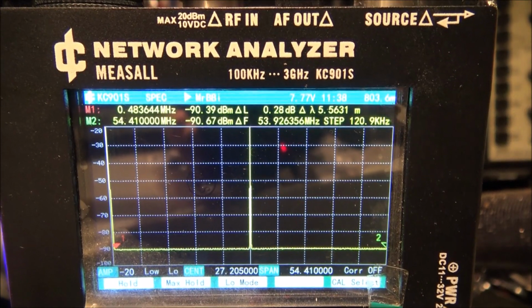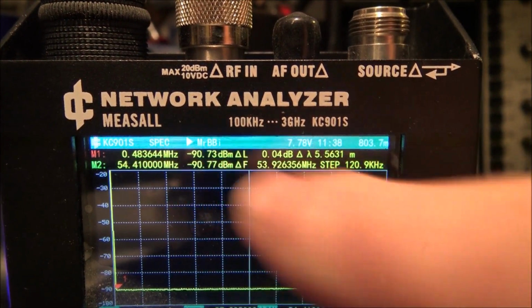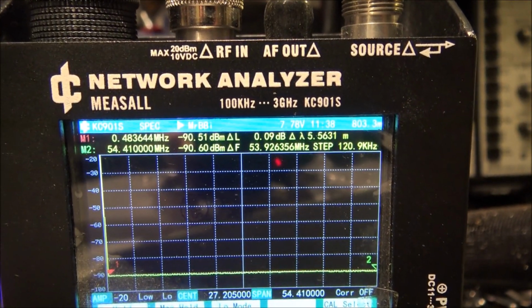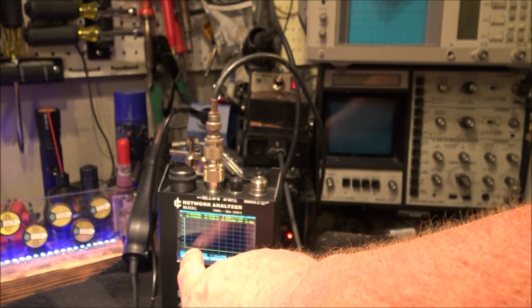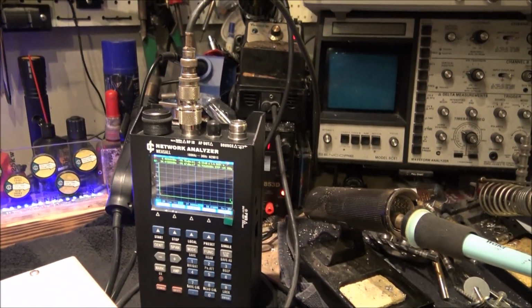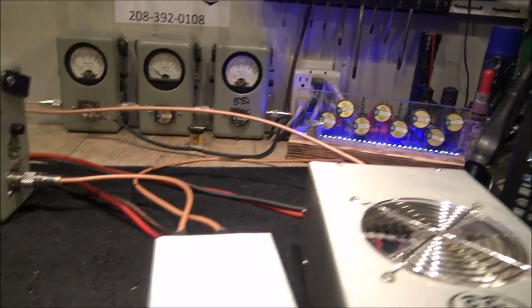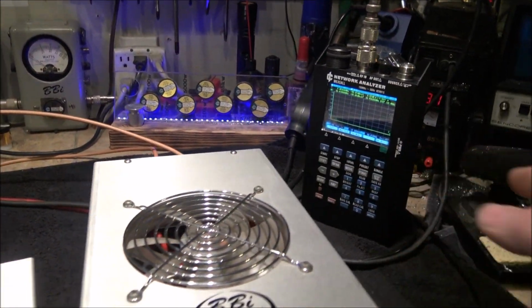And up here in the corner, you can see our signal reference. Okay, that's our noise floor bottom. If there's any kind of signal that is present out there, like I just seen a little bit of noise, I'm not even keyed up, just a little bit of noise popped in down here about 10-15 megahertz. It would show up on the spectrum analyzer. So now to protect my analyzer, I'm going to put that to pause.